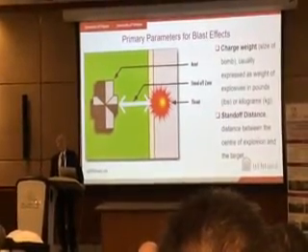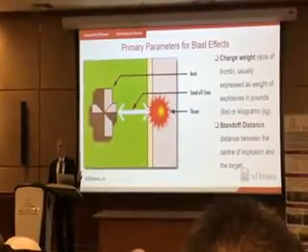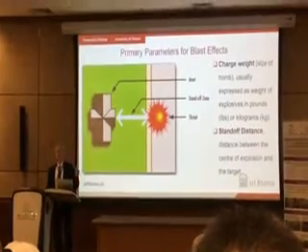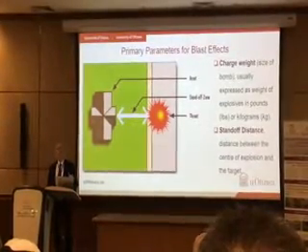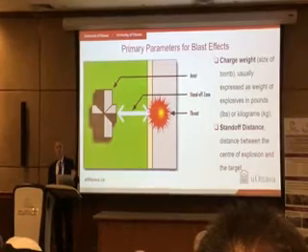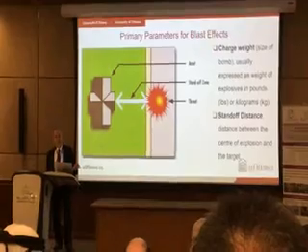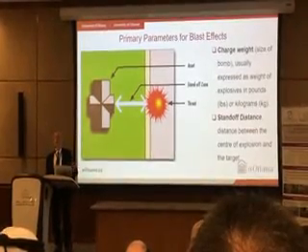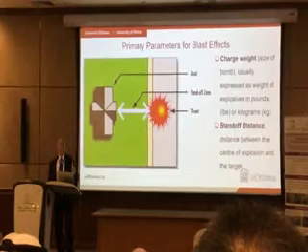Most explosives have the same detonation characteristics as TNT, but there's a conversion factor. Sometimes if they use ammonium, for example, you have to multiply by 1.2 to convert it to TNT. So in structural engineering, when somebody's talking about 200 kilograms of car bomb, they mean to say equivalent TNT. So that's number one parameter.